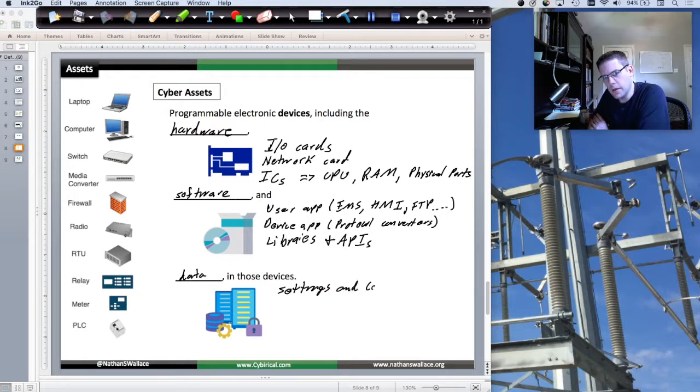and configuration files. So this is basically saying, okay, what's my impedance of my line? Where are my zones as far as my protection? If we're talking about a relay, what type of protocols are we converting? In the instance of the RTU, or even what type of automation we're implementing at that substation. If it's, let's say, an automation controller or a souped-up RTU. Any type of stored values.